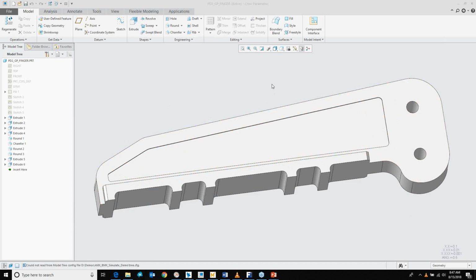And we've also done some prior analyses that also specify the optimal center of gravity that we want to have for this component right here, right? And that optimal center of gravity then means there's less of a moment arm for the motors to move this arm through, and the motors are doing less work, and we're optimized in terms of the kind of motion we want to get from this arm, right?